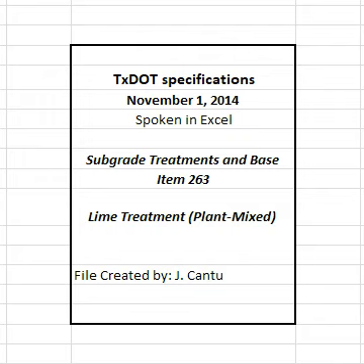Determine the moisture content of the mixture at the beginning and during compaction in accordance with TxDOT 103E. Begin rolling longitudinally at the sides and proceed towards the center, overlapping on successive trips by at least 1/2 the width of the roller unit. Begin rolling at the low side and progress toward the high side on super elevated curves. Offset alternate trips of the roller. Operate rollers at a speed between 2 and 6 miles per hour, as directed.